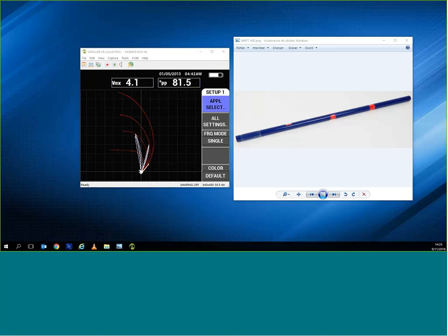So there you go. In about 30 seconds, I was able to calibrate the RFT absolute signal to fit my calibration standard. And now if I were inspecting a heat exchanger, I would just go in, start scanning, and figure out what's going on. So that's for remote field.